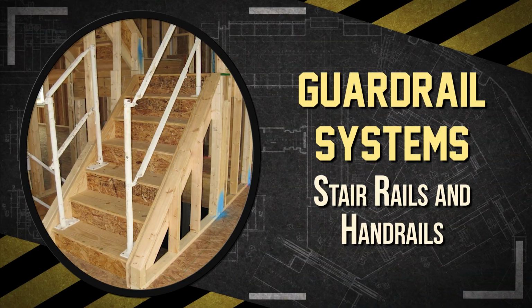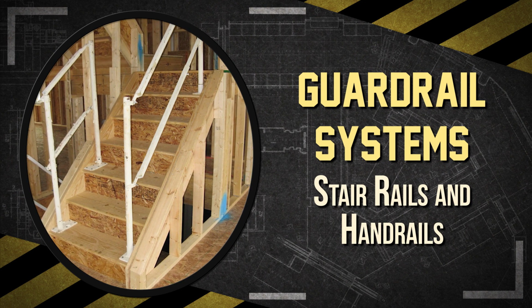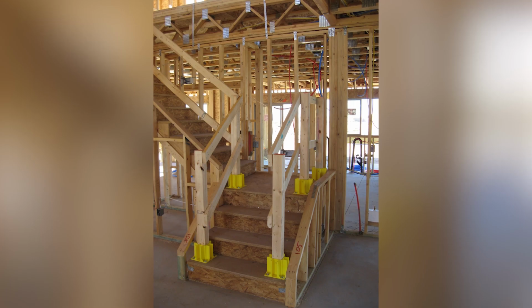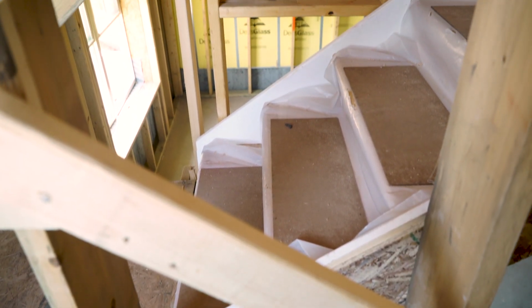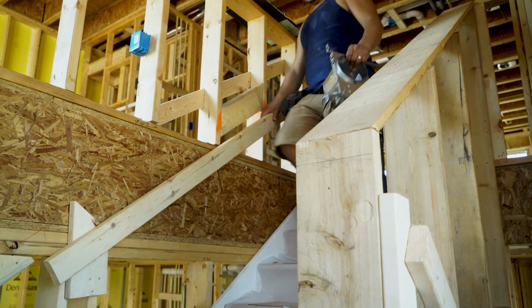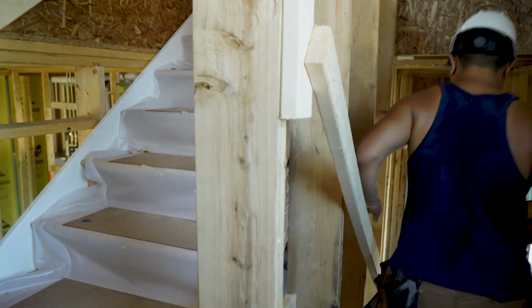Open-sided stairs present a fall hazard and must be protected the same way as floor and wall openings. Any stairway with 4 or more risers or a height of more than 30 inches must be protected by a guardrail system, also known as stair rails. Some stairs will require both handrails, which is a handhold for support, and stair rails that act as a guardrail. The easiest solution is to build your stair rails so they can serve both as the handrail and guardrail for an open-sided stair.